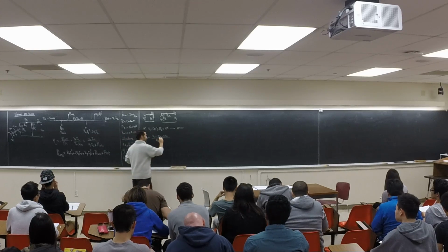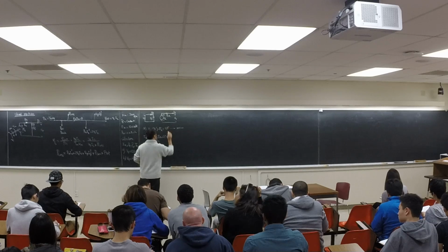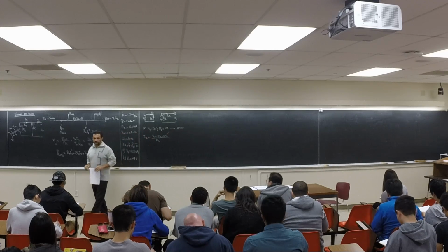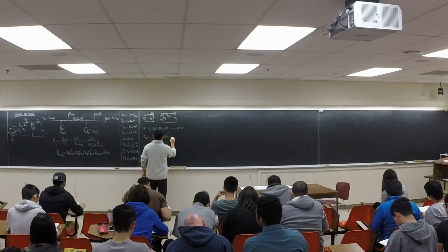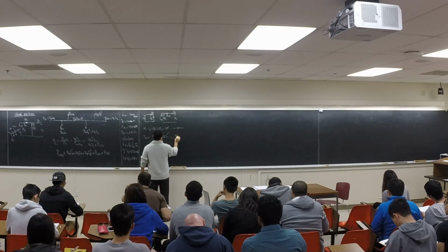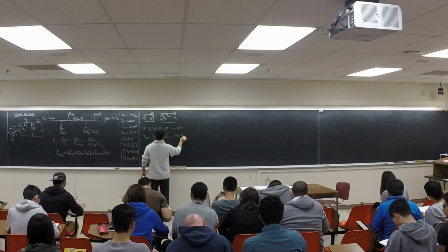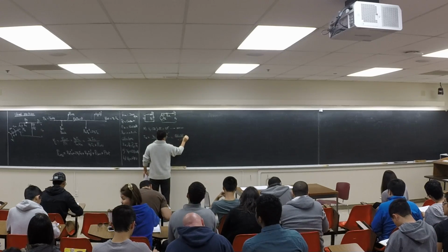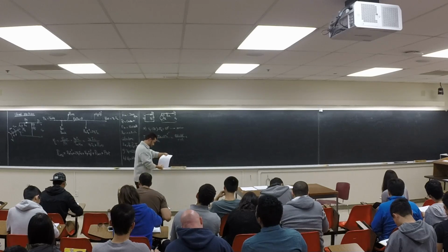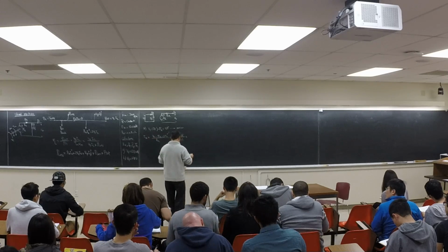But in this case, it didn't tell us anything about the brush voltages, so I'll just put 0 here, okay? Now, just to calculate, it's going to be 128 minus 125 over how much was the RA? 0.02. So basically this one is going to be 150 amps.